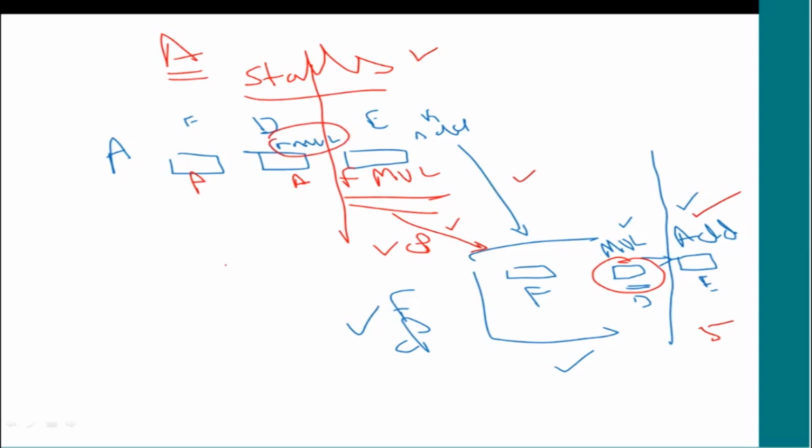The reason being, there is a coprocessor to take over this FML because CPA is 0. That means it is not absent. No, the floating point coprocessor is present, but CPB is 1. That means it is busy. So there is a guy who can take care of this instruction, but it is busy with his previous instruction. So now ARM has to wait.